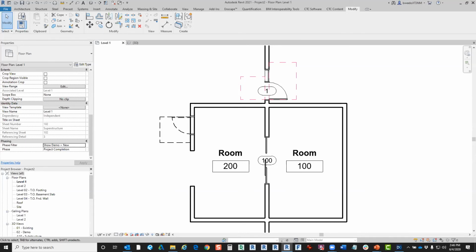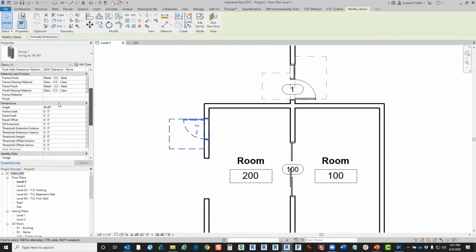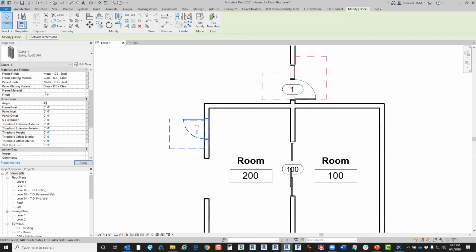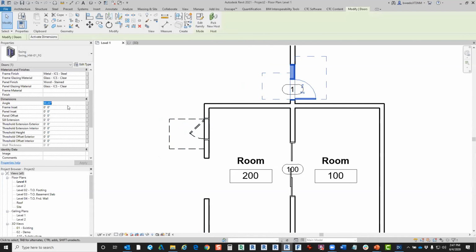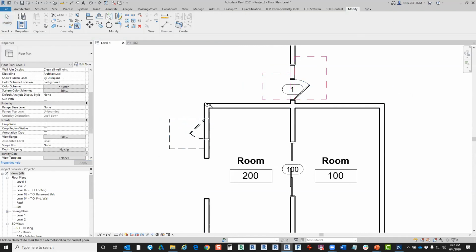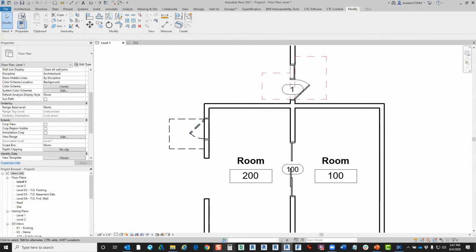Oh, okay. And Jason maybe had a side comment. As a company, they typically show existing doors in the correct phase, but show the swing as a 45. I don't know if you and Tim are at the same company. So in that case, yeah, that's an easy one too, because the swing is actually controllable as a parameter of the door, whether it's new or existing. So depending on how you want to handle that, that's a possibility. Thank you, Jason, for adding that.